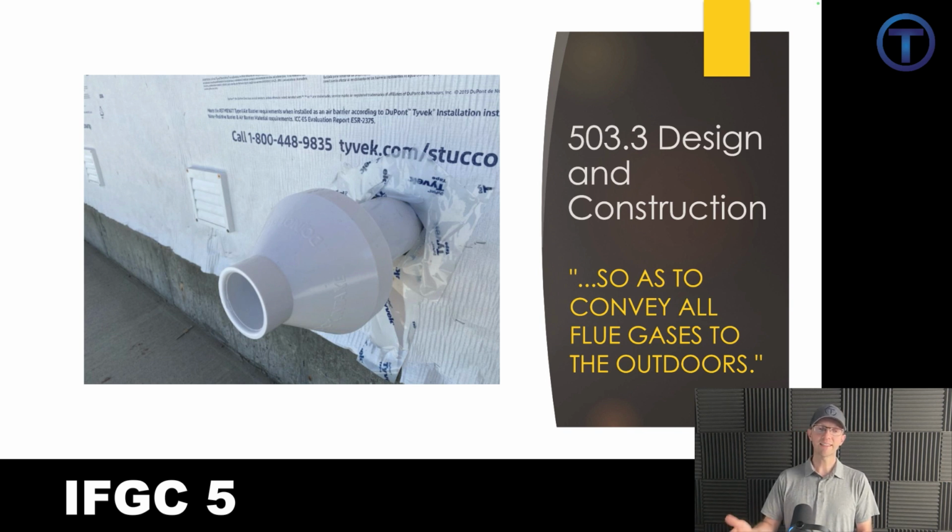503.3 says design and construction. These should be designed and constructed so as to convey all flue gases to the outdoors. That's really what we're focusing on in this section. All those appliances that were listed before that don't need to vent out, they don't apply to this. We're looking at running a pipe to get that flue exhaust out. All those gases need to be outside. And these have to be designed and built in a way that that can happen.